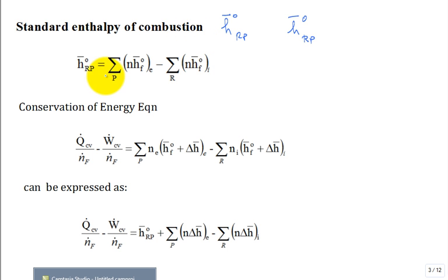And it's defined simply in terms of the enthalpy of formations. So it's like you took the general energy conservation equation, I just rewrote it, that's the one we just used, and we said, this term and that term times the standard coefficients are always kind of there. Grab them all, put them into one term. That one term is defined as this, give it a name. It's the standard enthalpy of combustion.